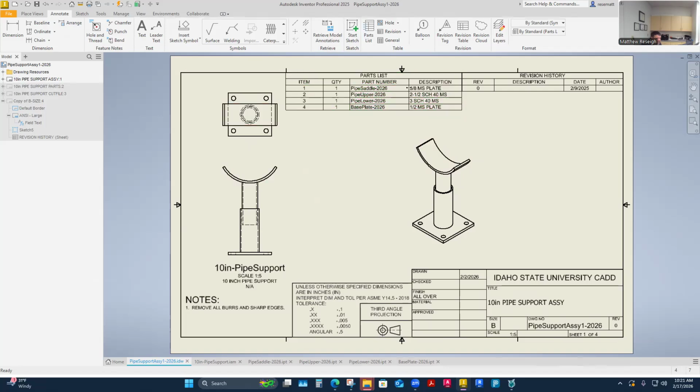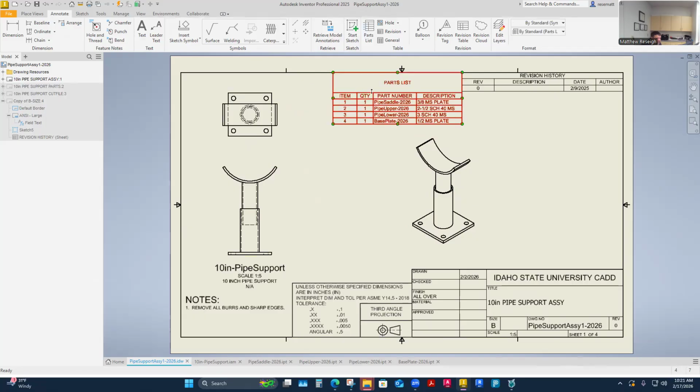I can shorten it up a little bit. Yeah, 3/8 MS plate, 1/2 inch MS plate. Oh, that's good. I like my descriptions here. Individual part numbers, quantities are called out, items. I'll balloon those things and come back to it. I mean to do that. There we go. Keep it small like that. So I'm just ready to balloon that, dimension that thing out, take one section view.